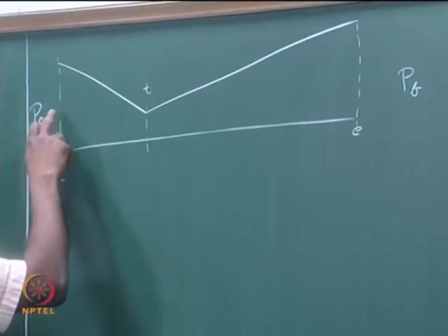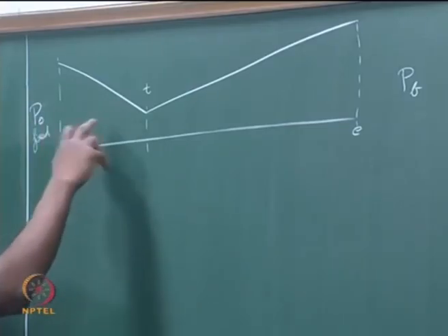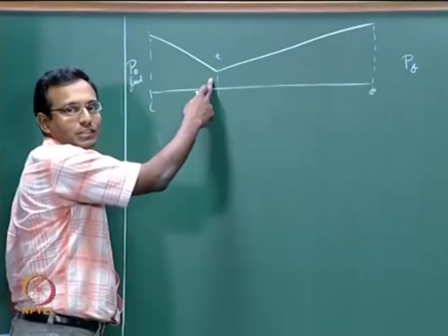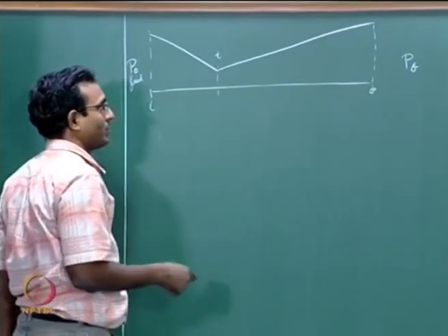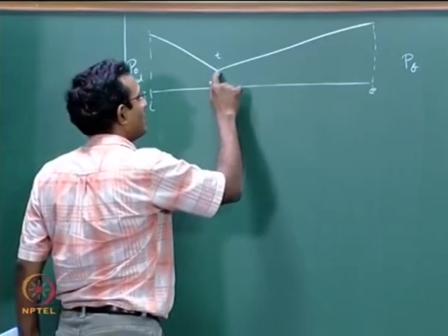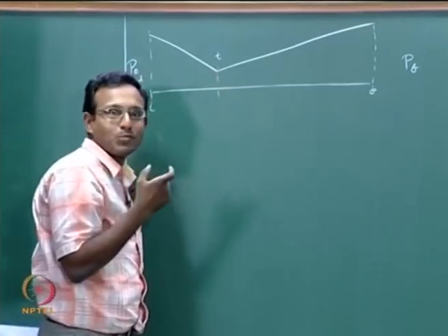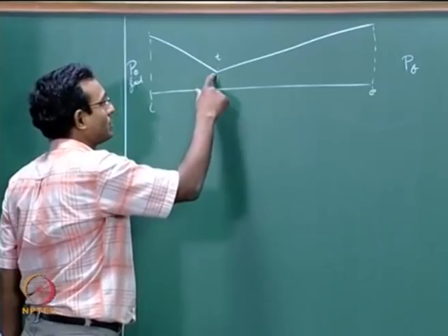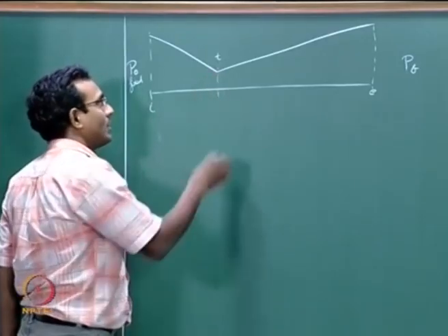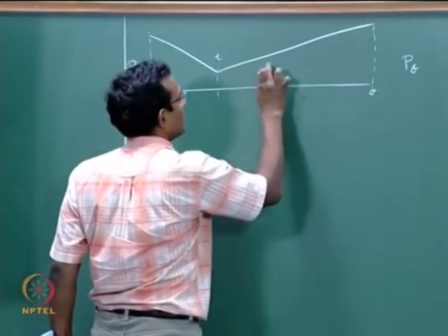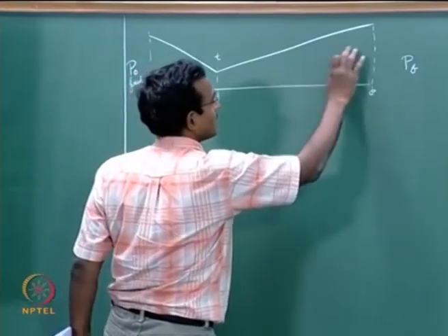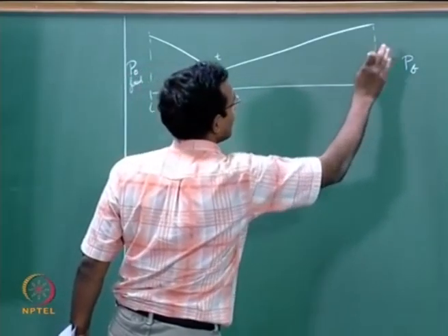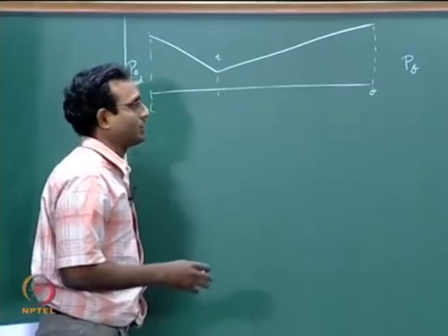It will be subsonic, and for subsonic flow in a convergent duct, the area decreases, velocity increases, and Mach number increases, and after that it will still be subsonic. I said it is a very small pressure differential, it is not going to get to sonic condition here, and after that it is again going to go subsonic, to lower Mach numbers, finally.